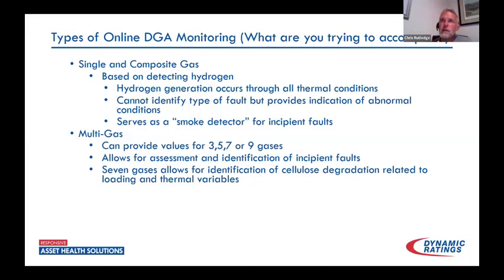So these through faults, every time that happens, we're seeing some shifting of these windings and also some thermal degradation that we're not necessarily going to see with other tests, outside of maybe a sweep frequency analysis, if we have a comparison. So that's something else that you may want to monitor. I think it would be an excellent idea to go through your transformers and say, hey, take the 5% of your fleet that's seen that highest level of through fault that year, and let's run an SFRA on those when we take them out of service and do our power factor testing.